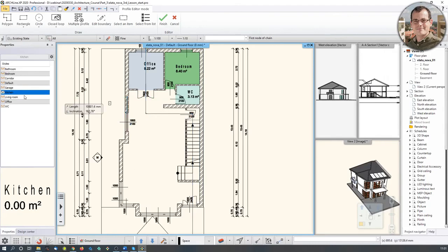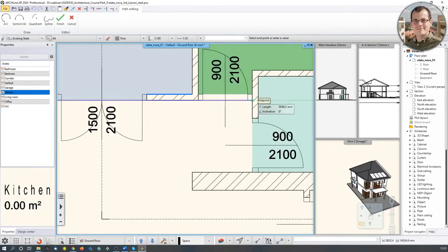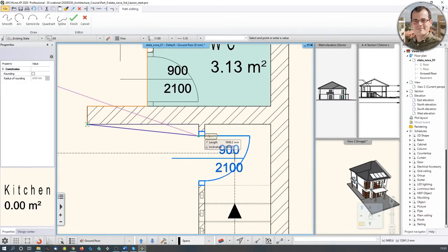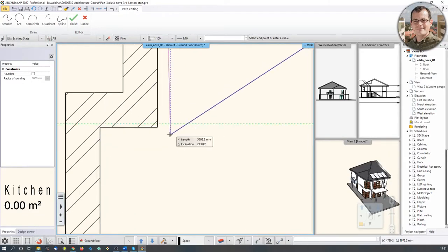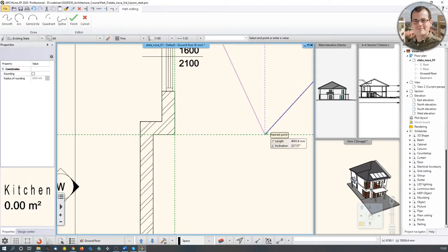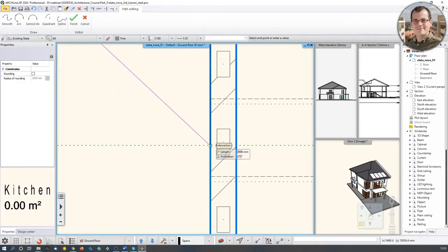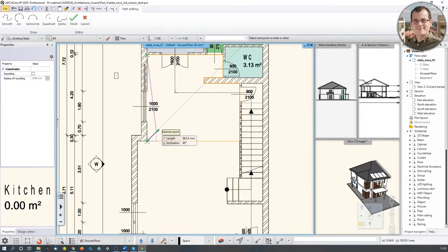And if I do that, first I define the role of this location, and then I can just sketch the polygon, any kind of polygon, by the way. And that way I can define how large this location actually is. Now, I want this line to go into this distance. How do I do that? I'm just going to hover my mouse to this edge. The green helping lines appear, and I'm just going to snap. You have to zoom in because this drawing is getting pretty dense. So I'm just going to click over there, hit enter.